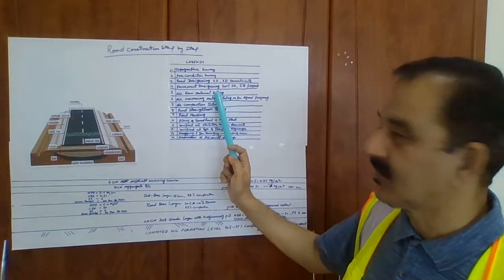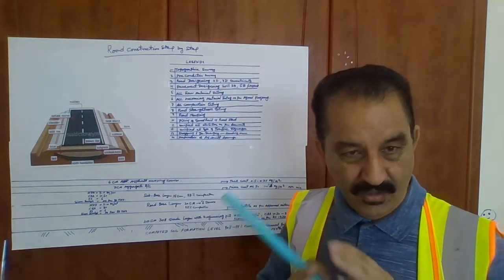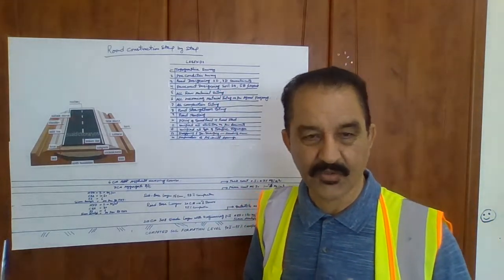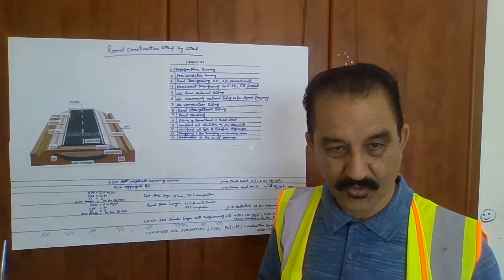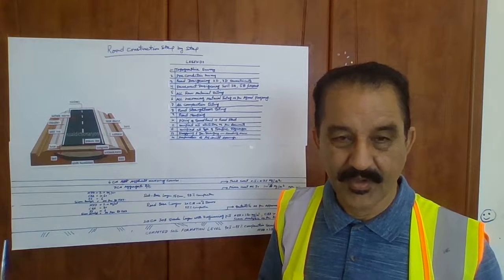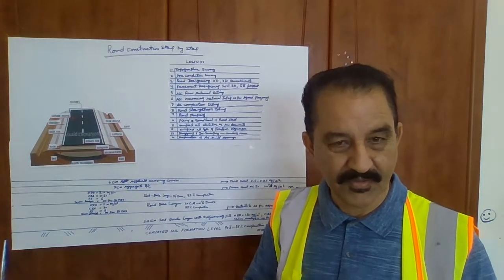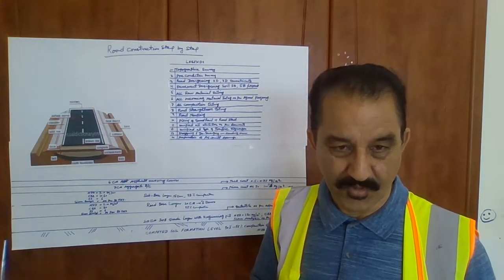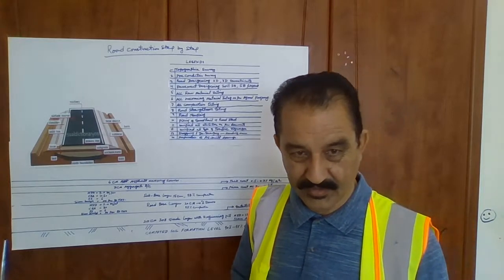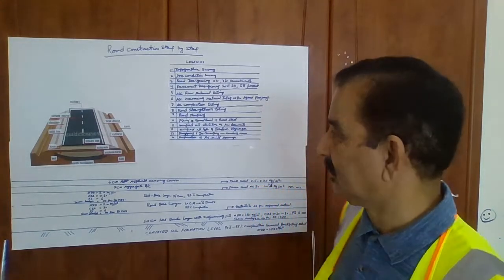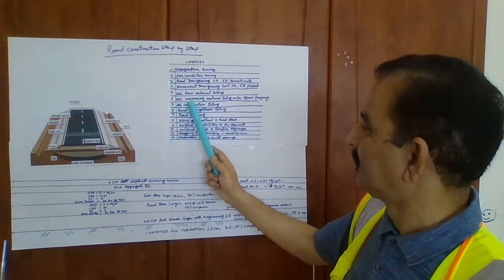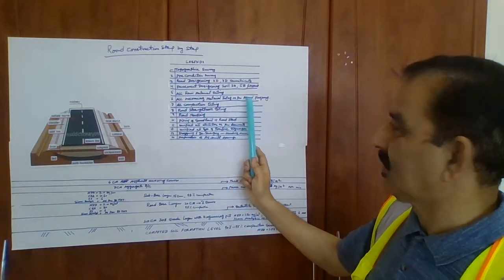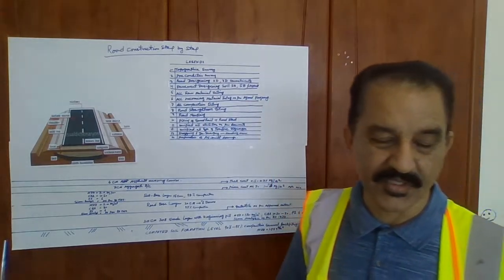Then all raw material tests. All the raw materials which are used for the asphalt and which are used in the soil, road base, subbase, subgrade, all the physical tests should be tested in accordance with the relevant standard procedure. And then number six is incoming material testing as per the agreed test frequency.